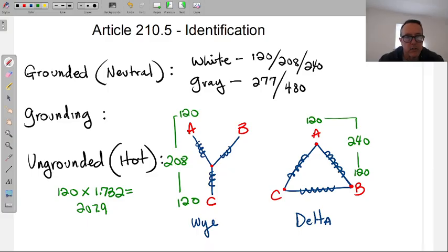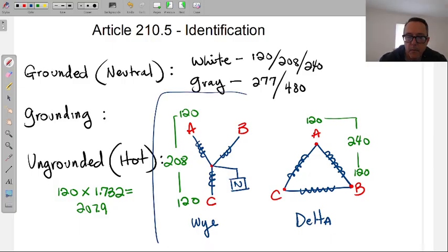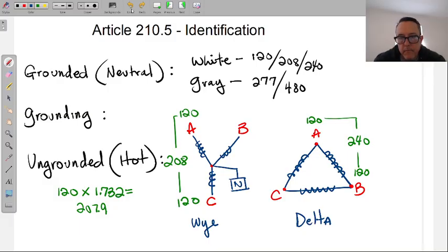Nothing, like I said, special about either one. The only thing special about the Y transformer, and you'll get deeper into this in code D, is that you get a neutral that doesn't have any issues. So these days the Y transformer has become the most popular out there, used in commercial and residential and industrial buildings. The one in our building, or the school, is a Y-fed transformer building.